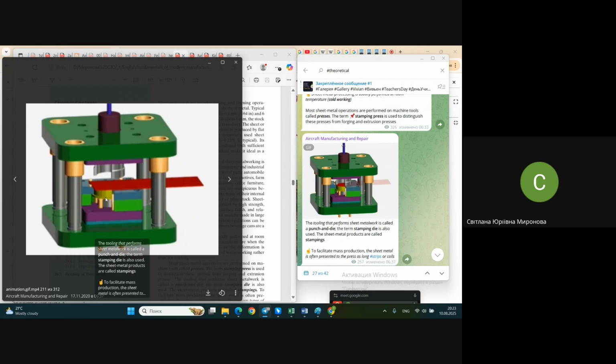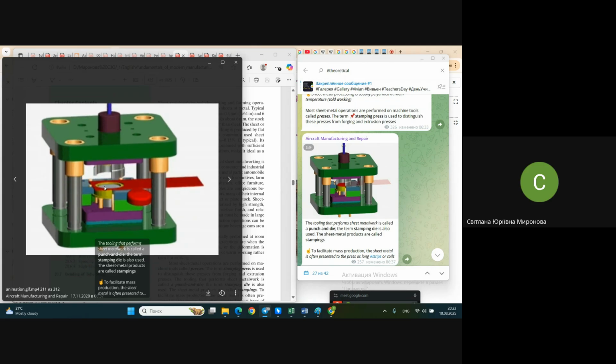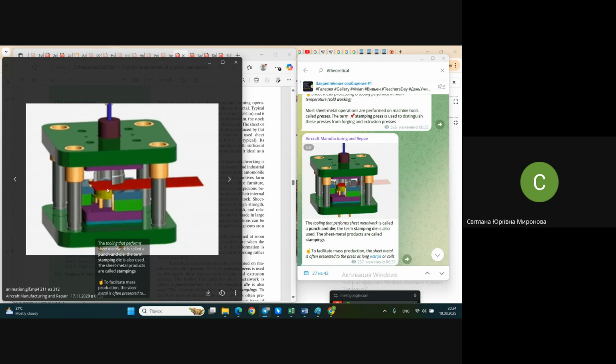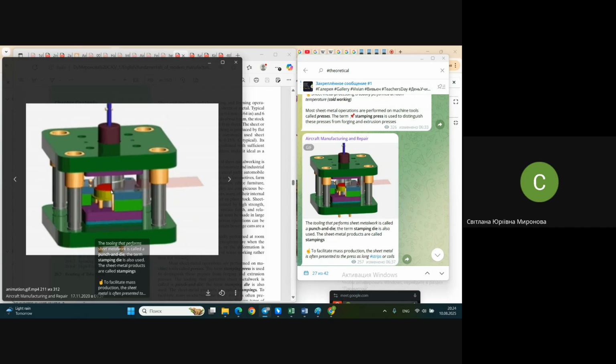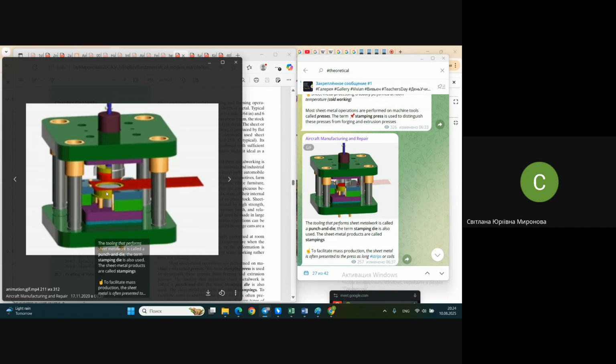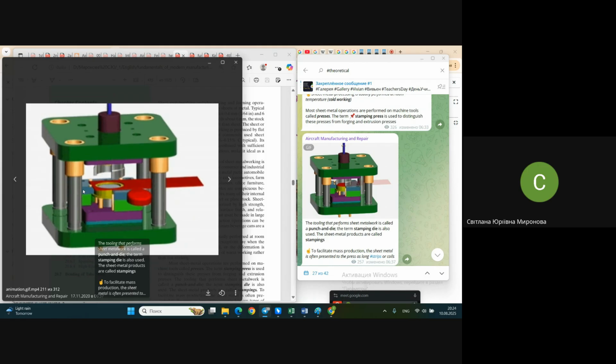The problem is it's a combined die, and here we have a punch. The cap is now placed onto the punch. The punch is this gray thing at the bottom. What you see in gray at the top is the die block for the punching punch, for the piercing punch, and at the same time the drawing punch in this case. And at the same time, it's the punch for outer cutting. And the die block is just a die block, here is this olive part at the bottom.